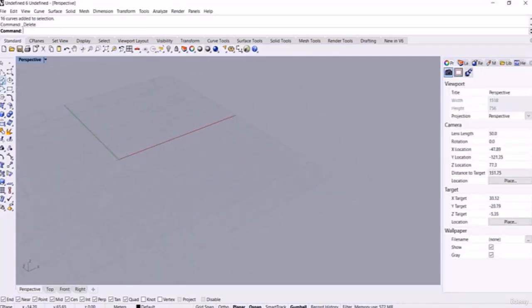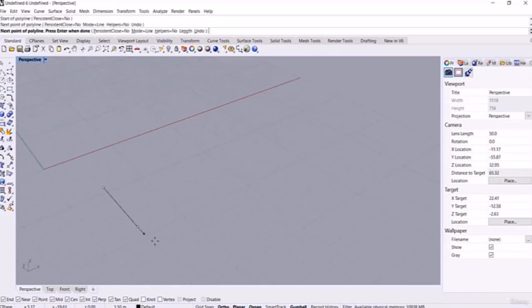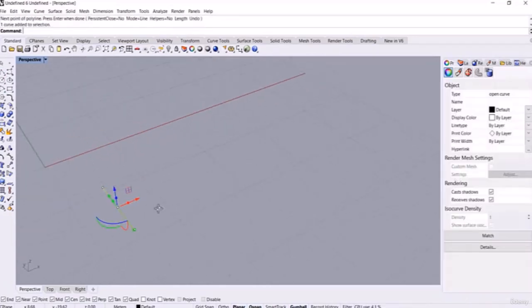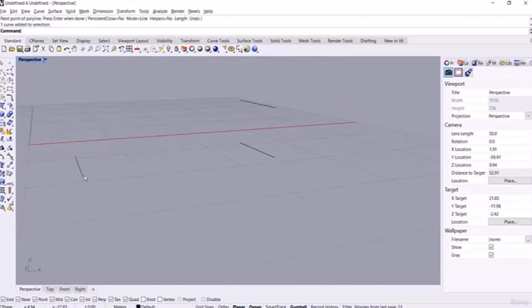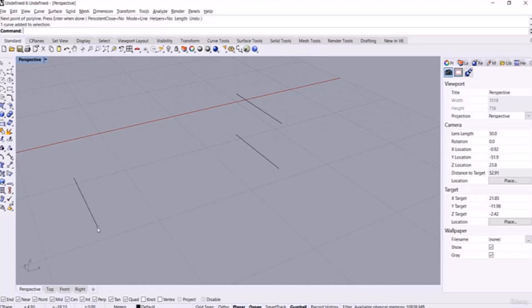And another application is that we can use it instead of array. Suppose that here we got a curve like this, and then I hold down Alt and click on it. Following that, I move it at the length of 20 units. Then at the other one I click, then I move it 3 units upwards. Let me move it 2 units more. Then in the continuation, I want to create 15 curves between these two curves, just like array.